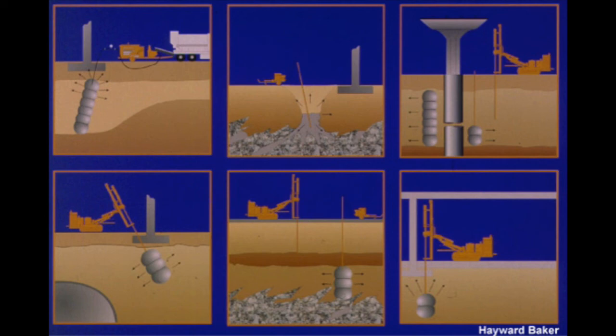Once again, grouting is the injection of materials by pumping into the soil or rock formation to change the physical characteristics of the formation. Compaction grouting is the injection of thick grout, typically a soil cement water mixture that has very low mobility. The grout remains a homogeneous mass and does not enter the soil pores. Therefore, it just replaces the surrounding soil with a substance of increased density. The picture shows different applications for compaction grouting, and as you can see in the top right, it is often used to strengthen the soil around a damaged pile.